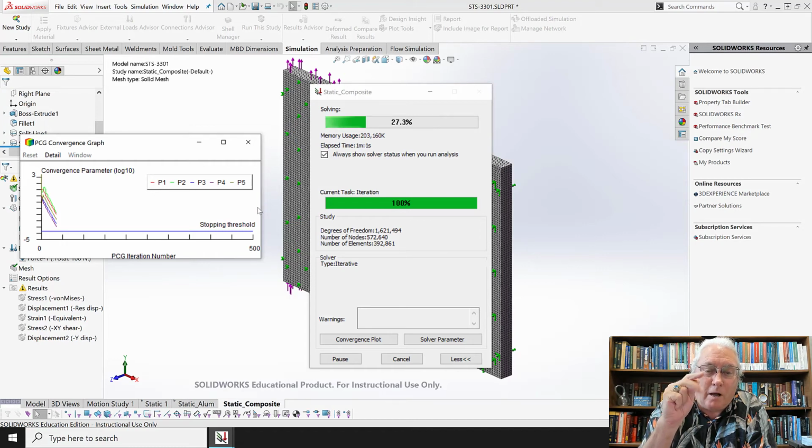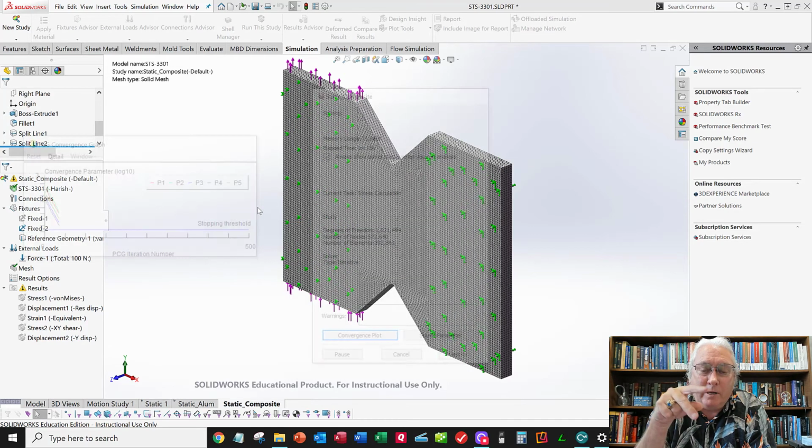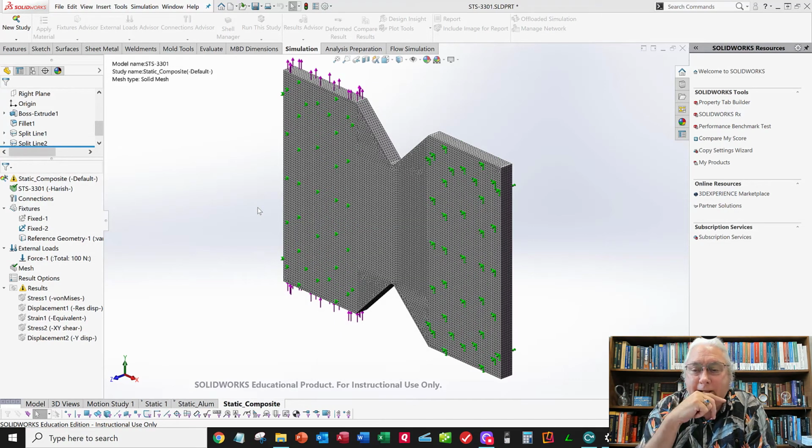And you can have first order polynomials, second order polynomials. In areas that have large gradients of stress, it will automatically, depending on if you're using a P method or I forgot the other method it uses, change that polynomial or change the size of the elements. But anyway, we need more videos here. So we'll talk about that another day.